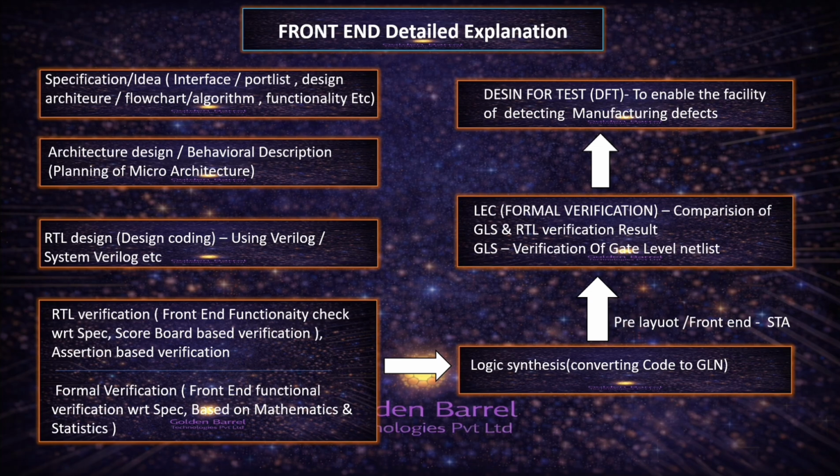Then after synthesis, we can do gate level simulation, GLS. The simulation will happen on the gate level netlist. See here, we already did RTL verification. That is not on a gate level netlist, that is on the design code. And this GLS is on the gate level netlist.